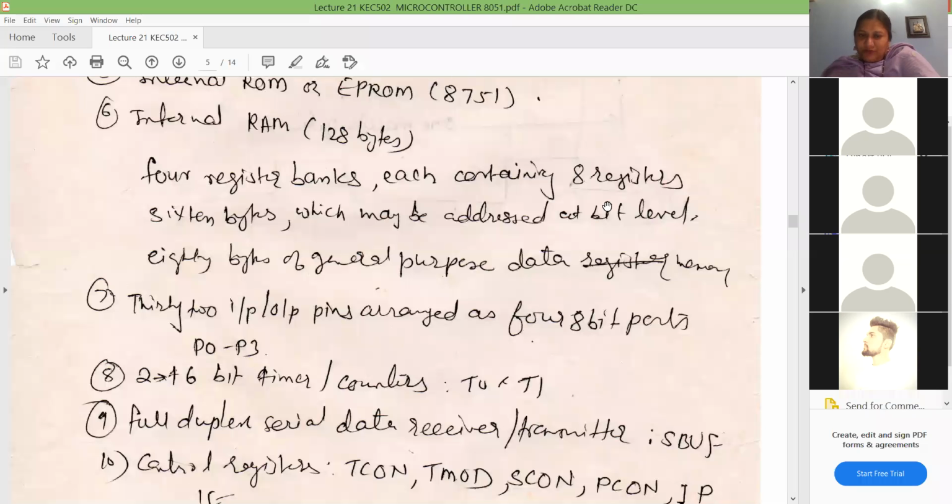That means you don't have to refer the whole register as R0. You can use a single bit of R0 register also. So likewise, how many bytes or how many registers are there which can be used as bit addressable area? It is 16 bytes. That means how many bits are bit addressable? How many bits are there which are bit addressable?